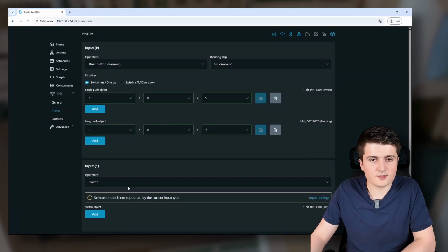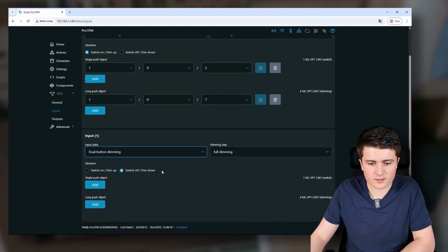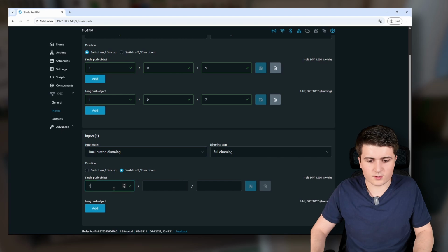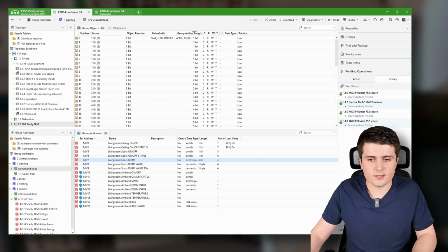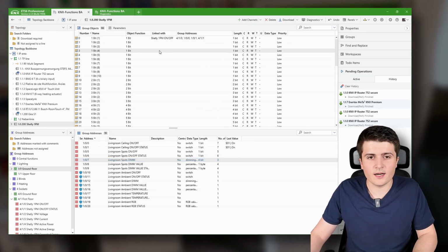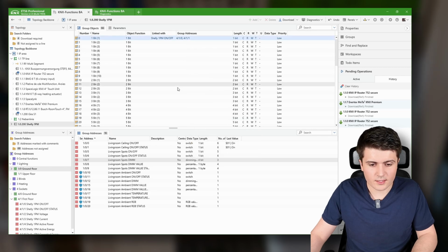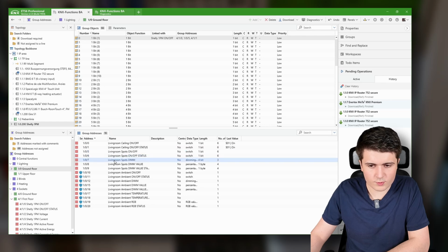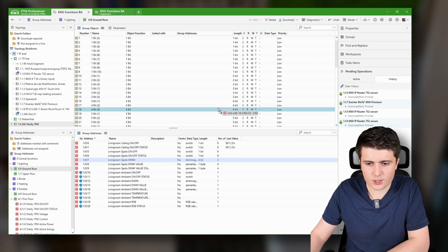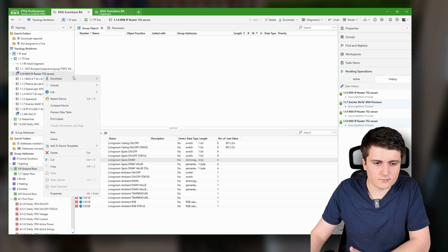And yeah, that's basically the same that we can do here for the other one. So dual button dimming, in this case off and dim down. And then we will add 105 and 107. And also here now we need to connect those group addresses to my Shelly dummy object here. So I can quickly unlink the group addresses from the living room ceiling and instead now use spots on off. And we also used spots dim, and now remember, dimming is a 4-bit object, so here we will use a 4-bit object for that. Now with that I download the router.